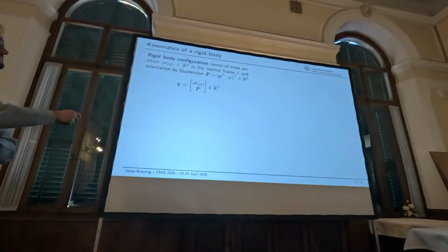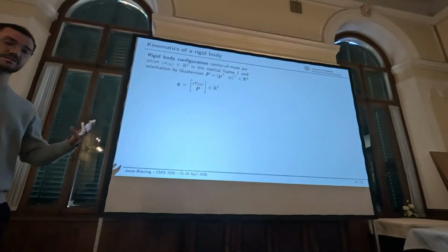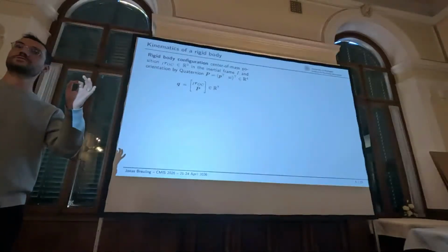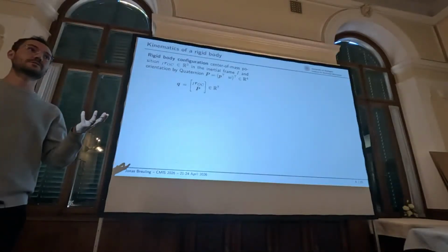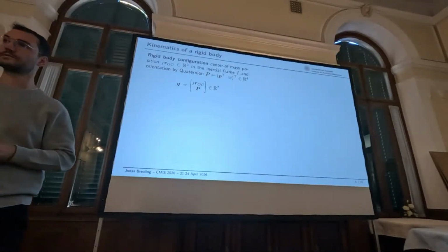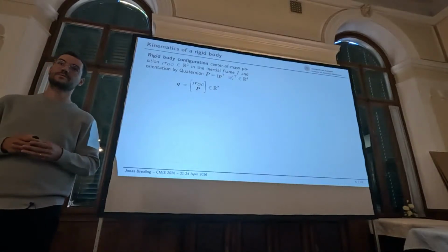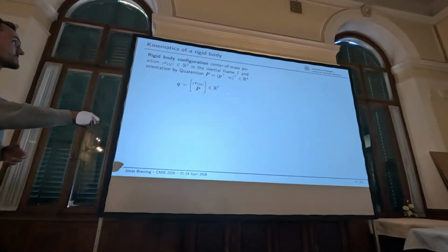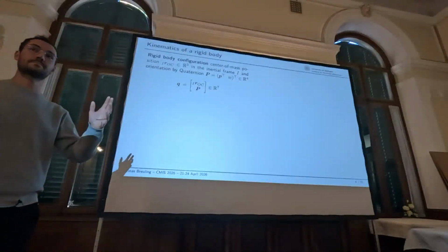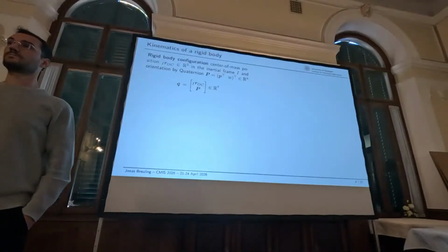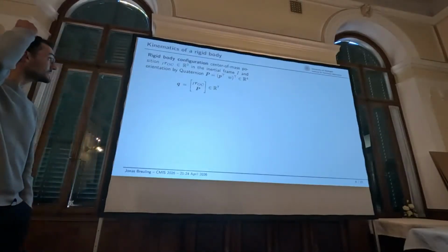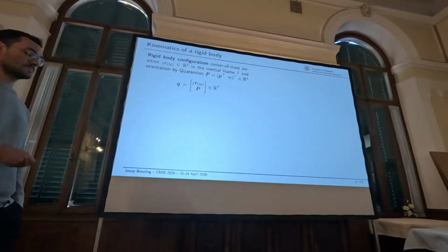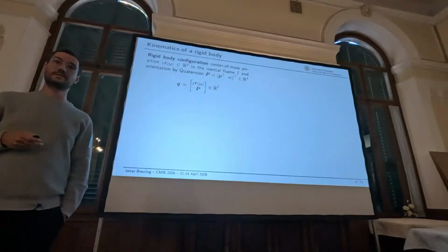The basic point is we have a configuration made of the center of mass of a rigid body, and we have to somehow describe finite rotations. It's classical to use quaternions there, which are 4 real numbers with some calculus rule behind them, and we can use them to have 7 coordinates for each rigid body in positions.